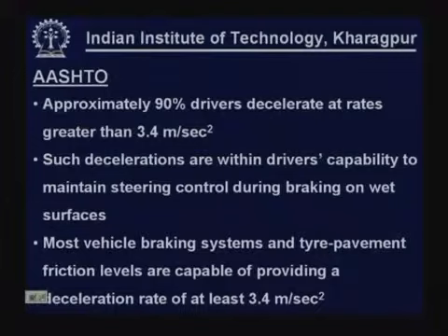Coming to the AASHTO recommendations, it is found that approximately 90% of drivers decelerate at rates greater than 3.4 meter per second square. Also, it is found that such decelerations are within driver's capability to maintain steering control during braking on wet surfaces, because wet surface is critical as compared to a dry surface.